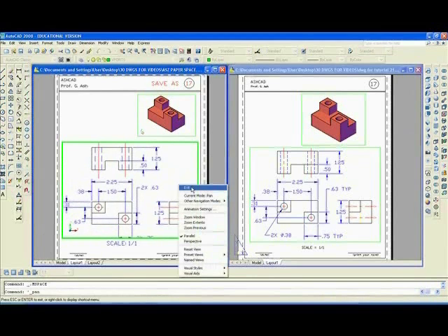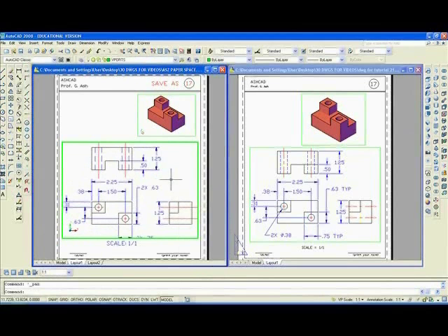You can see that the center lines don't look all that great, so I'll type LTS again, and this time I'll make it even smaller. Let's try 0.5. That looks better. Now we'll save this as exercise 17, and I suppose we ought to complete it.